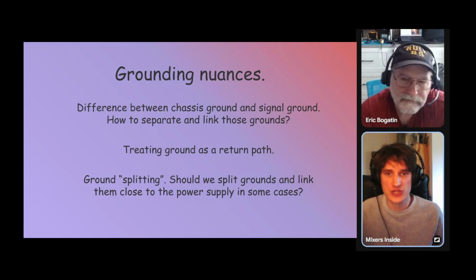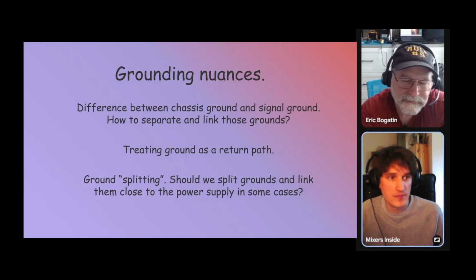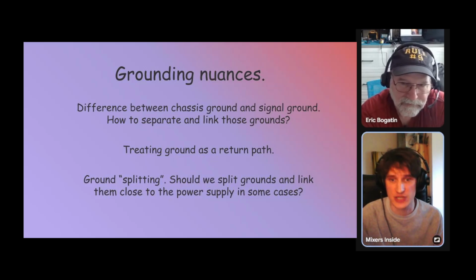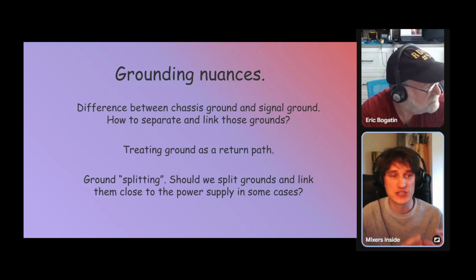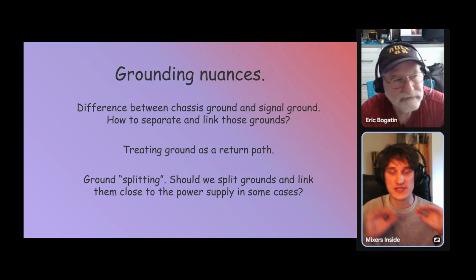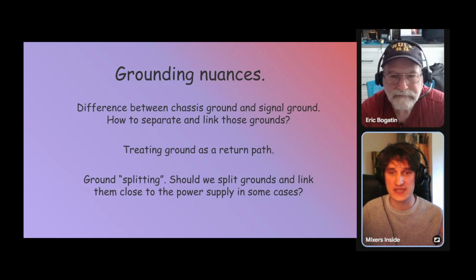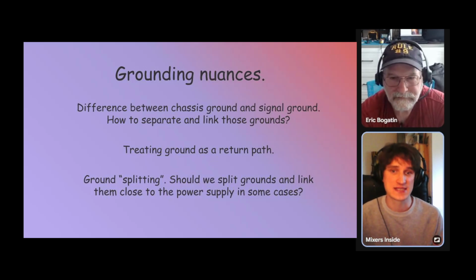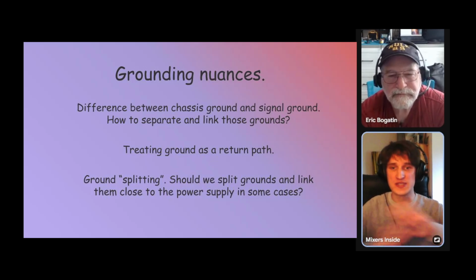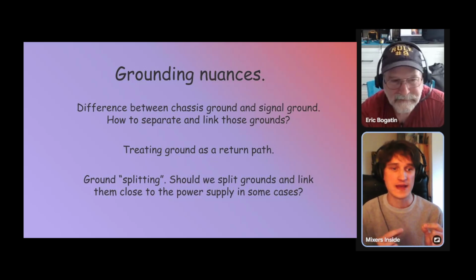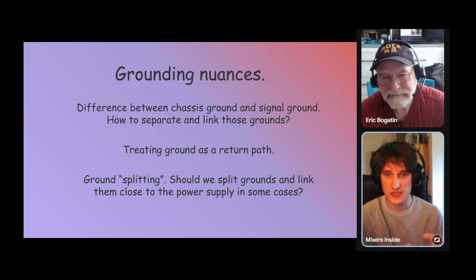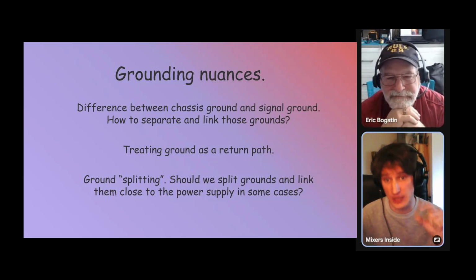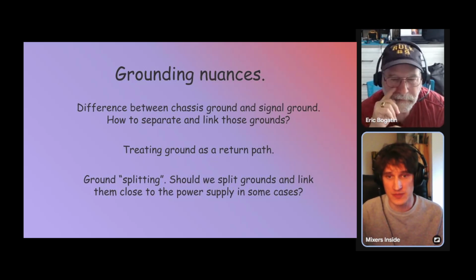And now modern literature, mainly from the point of view of EMI and interference, says that the solid ground plane is always the best solution because it provides you very low impedance. As you said, the ground plane is just a piece of copper, and the voltage drops during interference will be kept low because of the low impedance, right?